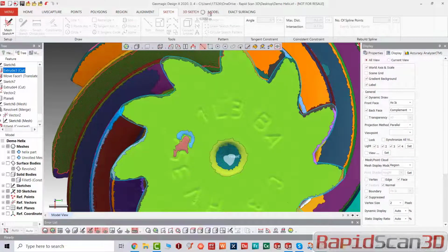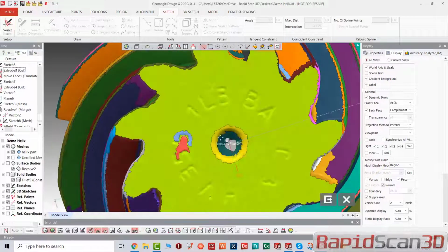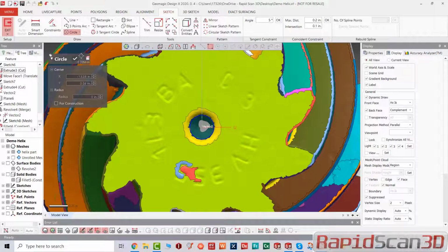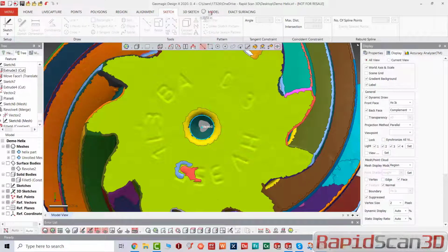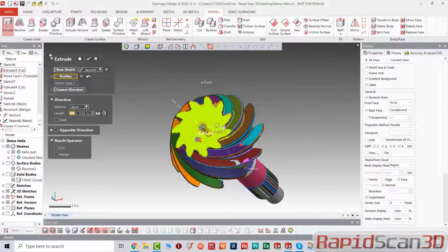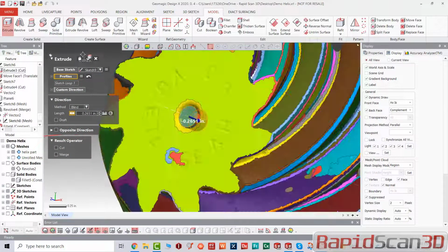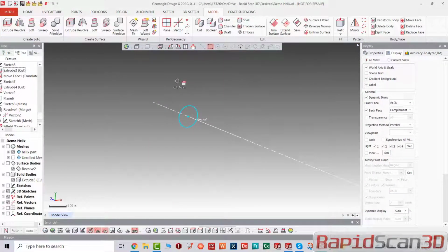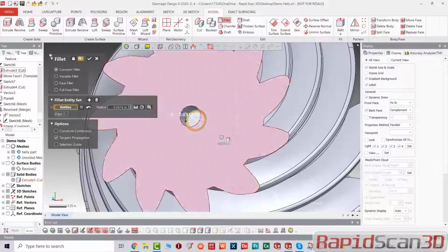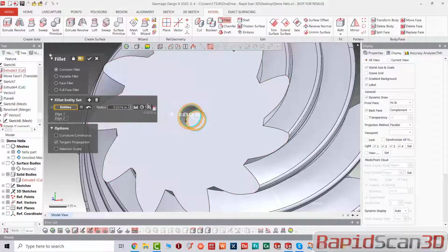We're just gonna go ahead and create a little circle in the center. And then drop it arbitrary. We're just gonna cut it almost a 1/4 inch, and then put a fillet inside and out, and estimate.